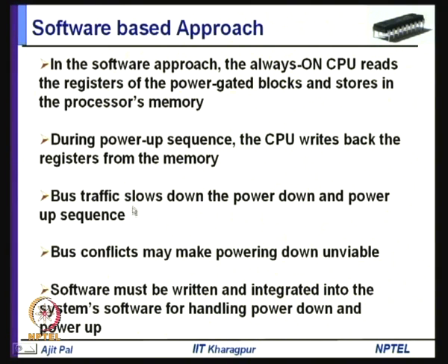Whenever you do that, the storing and loading will take place through the system bus, and this will definitely influence the traffic on this bus, and bus conflicts may make power down unviable. So, there may be bus conflicts, and that may lead to unviability of this approach, and software must be written and integrated into the system software for handling power down and power up. So, you have to write appropriate software which will take care of this.